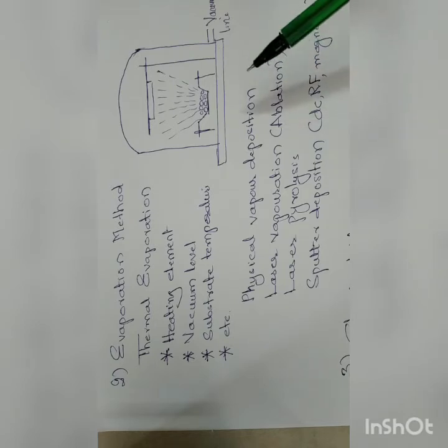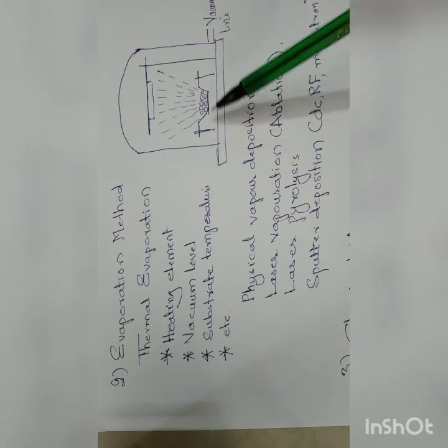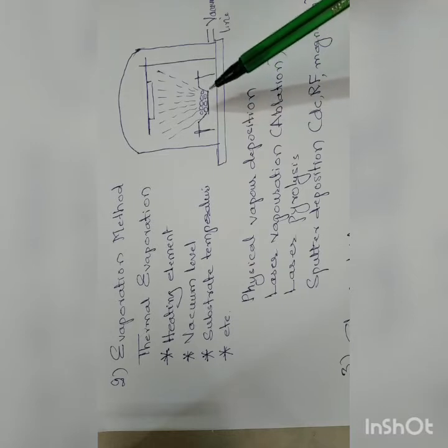In this process you can notice a very important thing. You take a material, you have an electric heater, you heat it to the required temperature, you vaporize, and the vapors will go and condense. But we know that when we heat any material in open conditions up to the melting or vaporization temperature of the material, the material will react with atmospheric oxygen. The result of that is the material becomes an oxide rather than the original material.